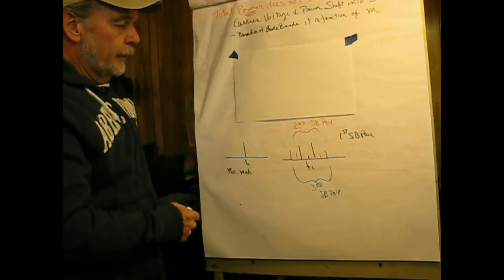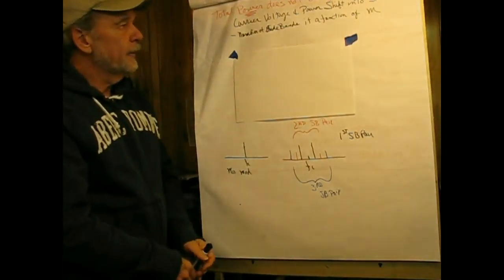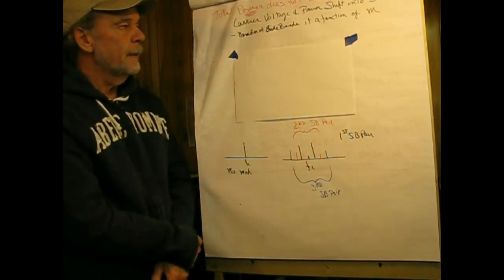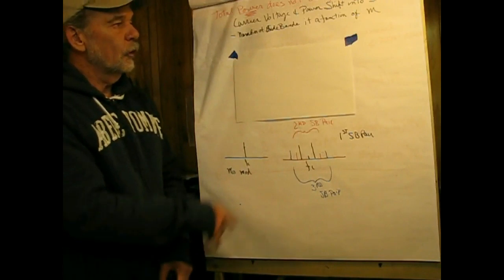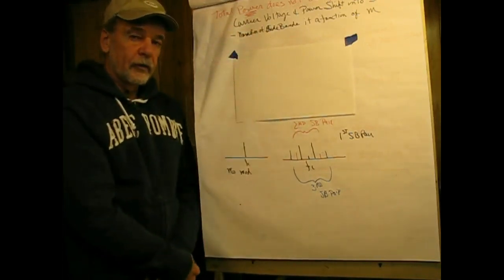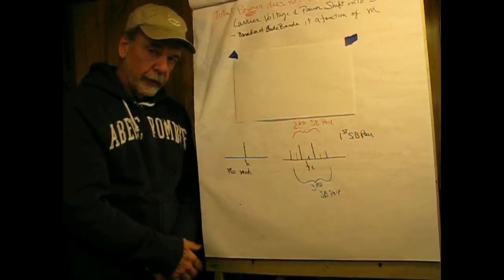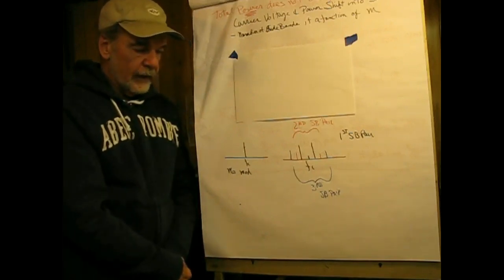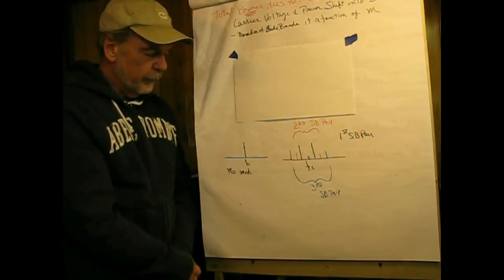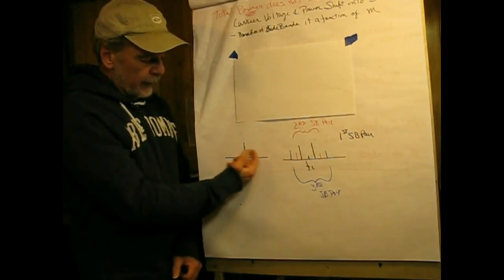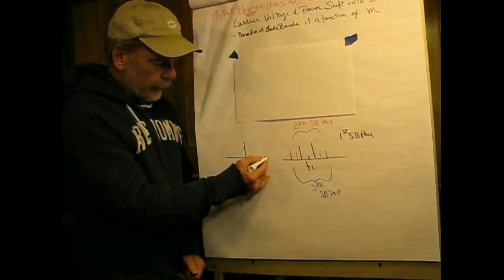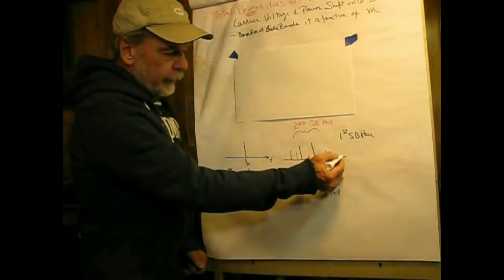Okay, we're going to get into some details here in a minute, but again, total power does not change with modulation, and the carrier voltage and power shift into the sidebands, and the number of sidebands is a function of m, the modulating coefficient. Now with a sine wave, unlike AM, we can have more than one sideband pair. So down here I've kind of illustrated that, and this is going to be in the frequency domain. Let's put a little F there, and I'll put a little F there.